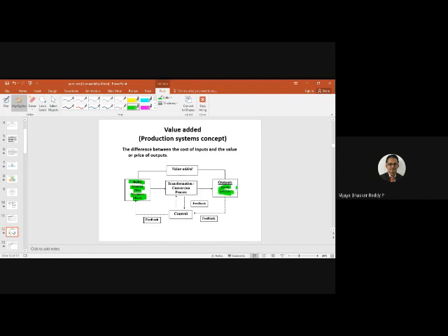Now we receive the material and start the conversion process. As you know, various stages are there. First, receive the raw material and check it as per the specifications, and do capacity planning of the resources. Then proper scheduling, with line balancing techniques. Whether it is mass production or batch production, we can classify it, and based on that we can identify the general process that we can use for conversion.